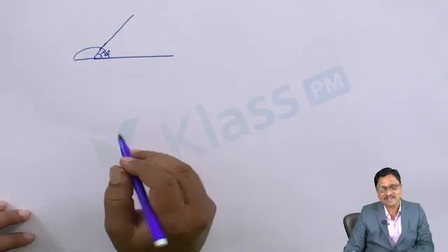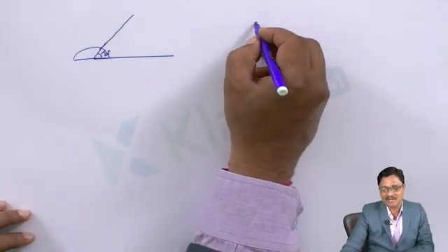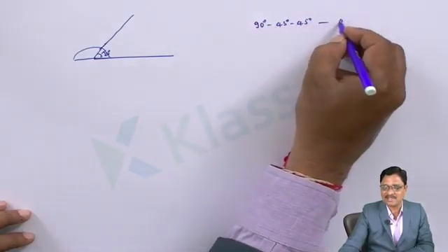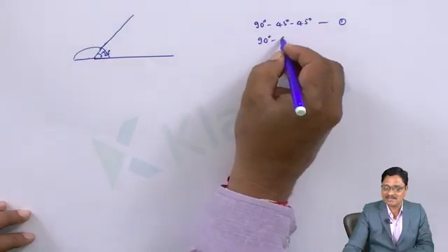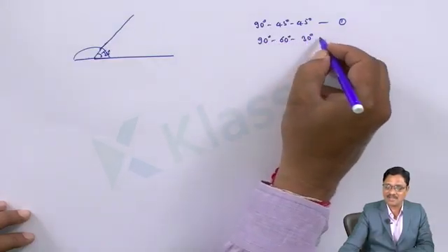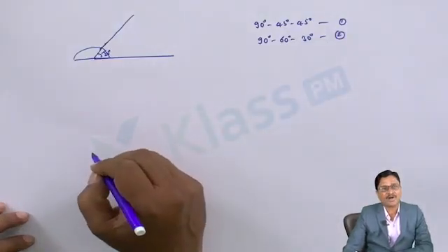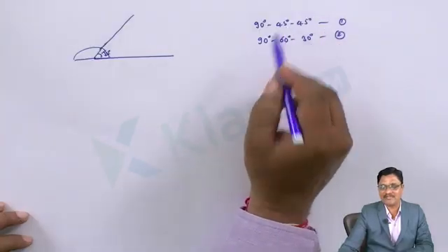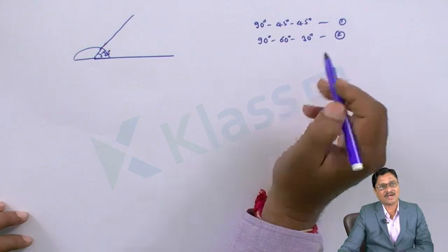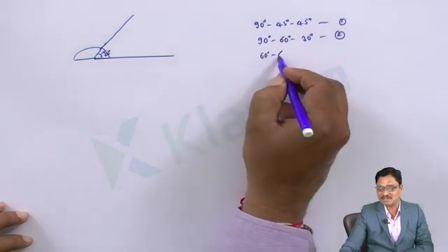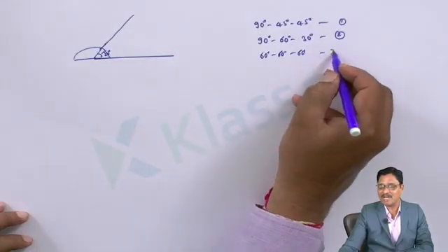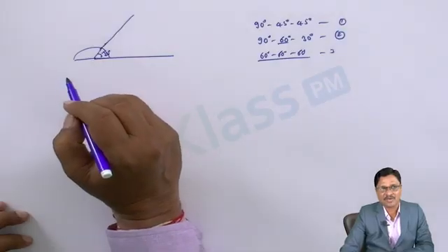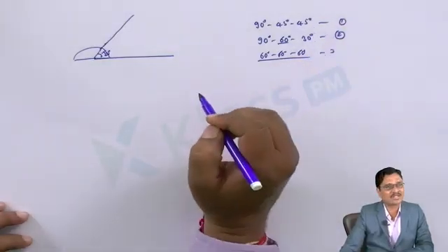Whereas the set squares are available normally as 90, 45, 45 degrees as one set, and 90, 60, 30 degrees as a second set. What are the standard angles? In both sets we have 30, 60, 90, 45, and by combining the two we can get more. The third one, 60, 60, 60, is also available, but it is not popular, since the 60 degrees standard angle is already available in the second set. Most popularly we use only the two set squares.